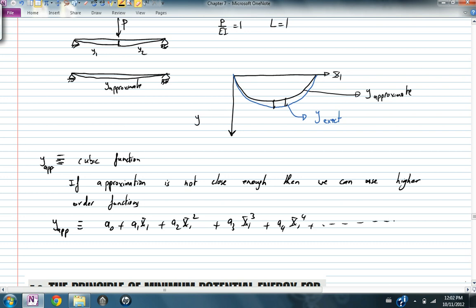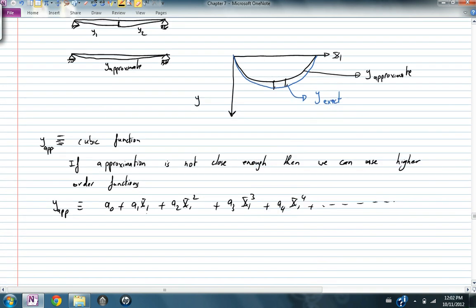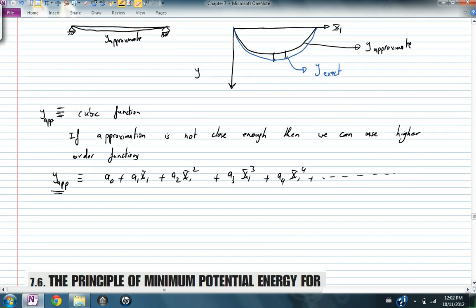And this is exactly how the finite element analysis method is actually implemented, using the virtual work and using some approximations for the displacement of the structure. We start with an approximation and we're looking for these constants, and so we utilize the principle of virtual work, equate the internal virtual work with the external virtual work to find estimations for these constants for the approximate solution.